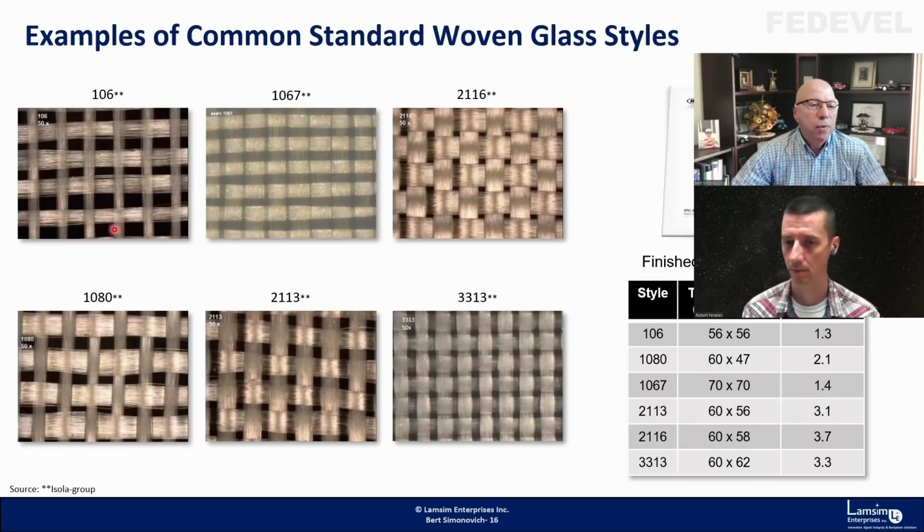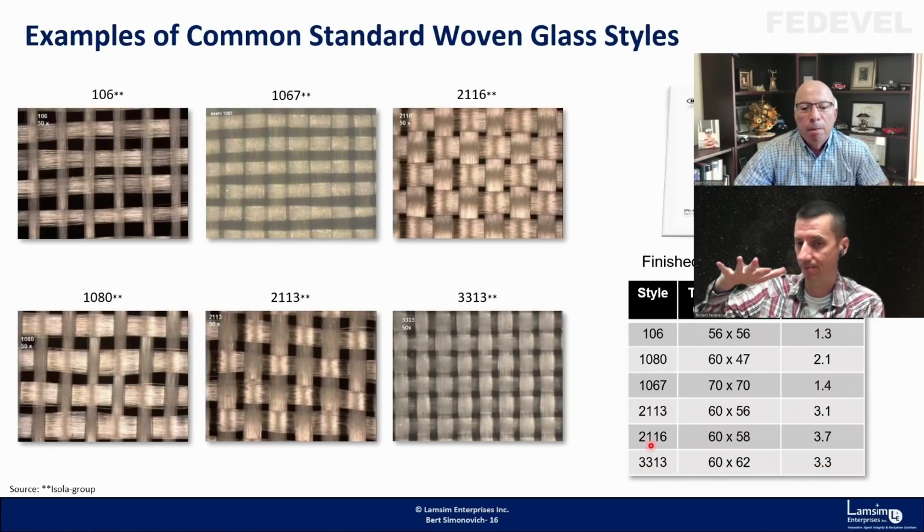So board shops have a DK/DF table. They have different thicknesses of prepregs and cores, and different glass styles, what they call. Basically, if you go for 3313, then the minimum thickness is like 3.3 mil. That's quite low. Right, exactly. And then they build laminates. So if they want a 6 mil laminate, they'll say use 23313. But then you will have the layers further away from each other when you use this.